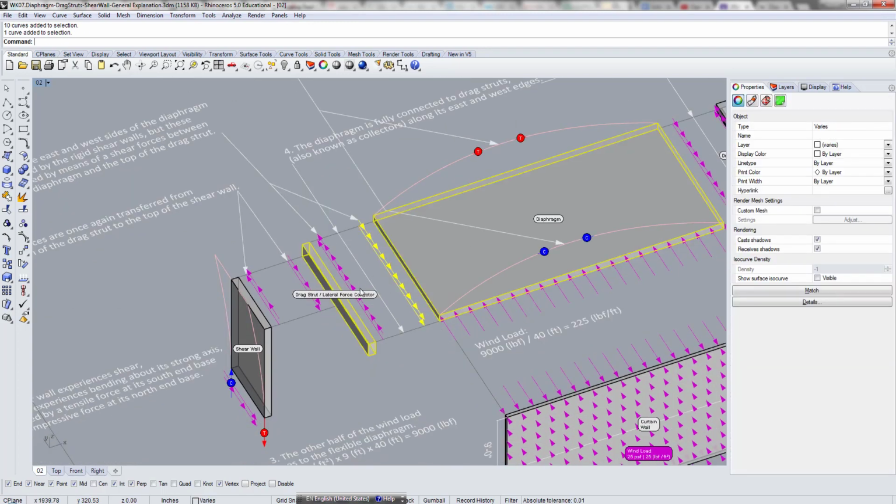But if you remember what shear is, this is why these walls are called shear walls. If you remember what shear is, even for a beam or whatever, if there's a force this way and that way, there's a tendency to try to slide these two elements across each other. So that's what shear is, right? And that's exactly what's happening between these three things, right?